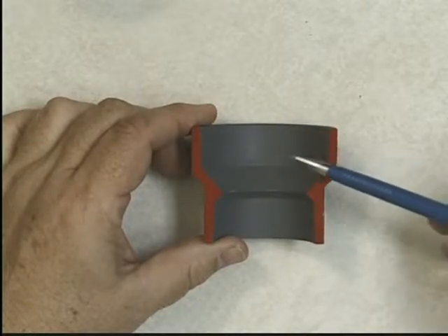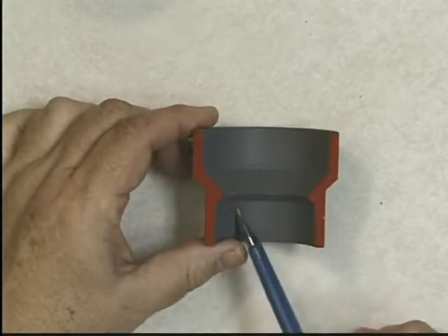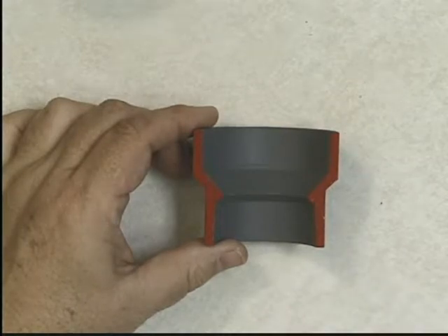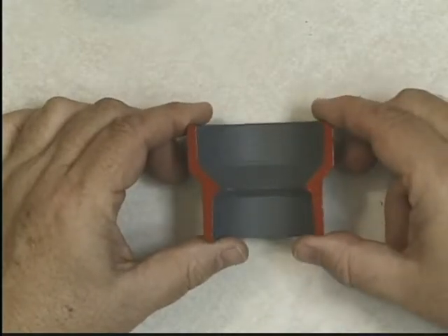And I'll show the interior just as if I was looking at it, with these intersections of surfaces shown as solid lines. So there's a full section view of this little flange. Let me show you, since it's symmetrical, how it might look if we did a half section view, because I happen to have cut another one.